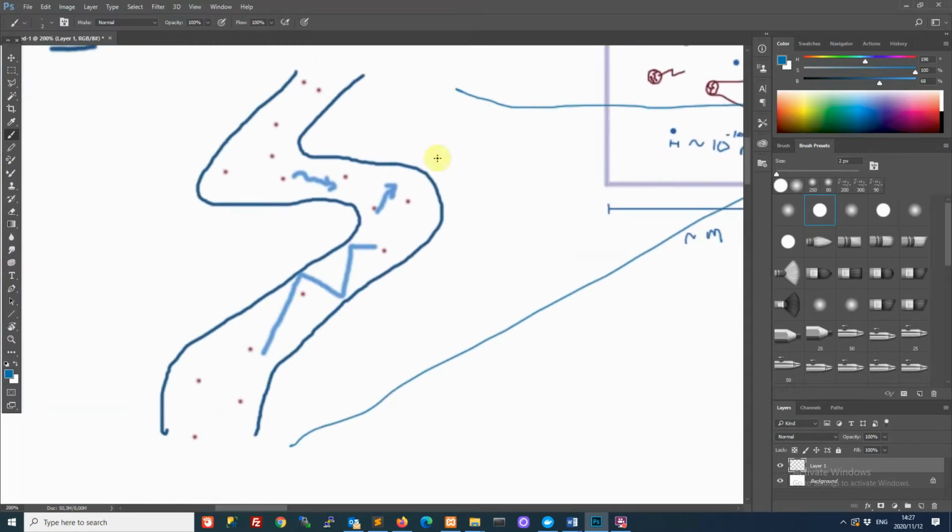your pore might look like this, and now you see your pore is actually on the same scale as your molecules. So if that's the case, then you will have collision with the walls of this pore. And so this then starts to rival the interaction of molecules on molecules. So if this was a binary mixture of A and B, let's say I'm drawing component B now, we would like to estimate the diffusivity of A in B. But now we can see that A is also going to be knocking around against the walls of this pore as well.